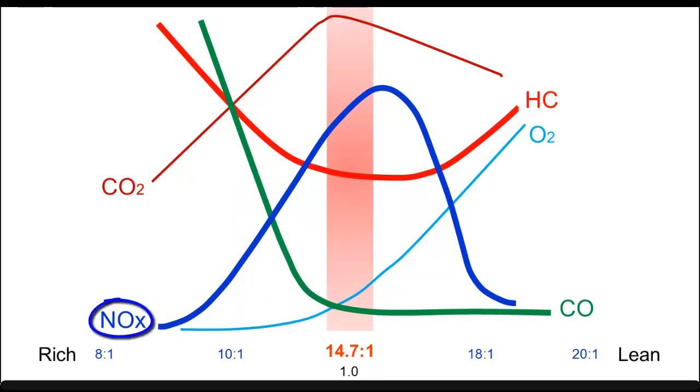NOx emissions remain low at 1 part per million. Carbon dioxide is off-peak, low at 6.85%. Oxygen is 0.81%. Lambda at 0.70 indicates richness.